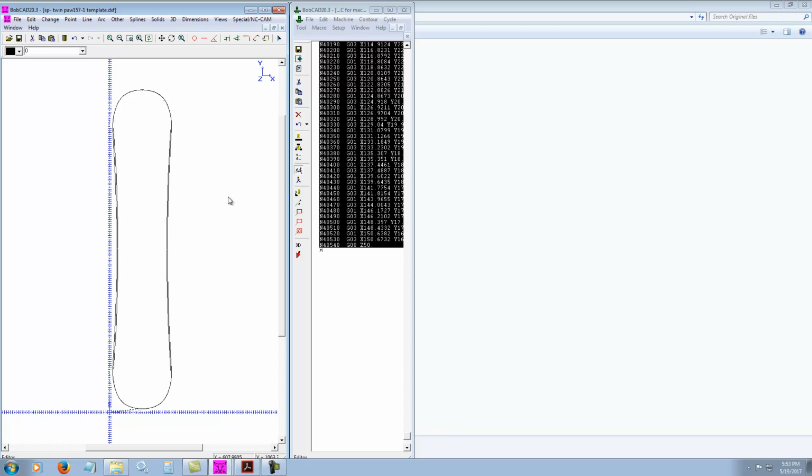Now I'm going to click on this and go Control Z on this left side just to undo that last step we did, because we don't want that line. In fact, I'm going to undo the other step here. And that gets rid of the outside line, and we've just got that shape file that we originally started with. You see that if I'm doing it on the left side, it doesn't affect what's going on the right, where we've still got all our code.